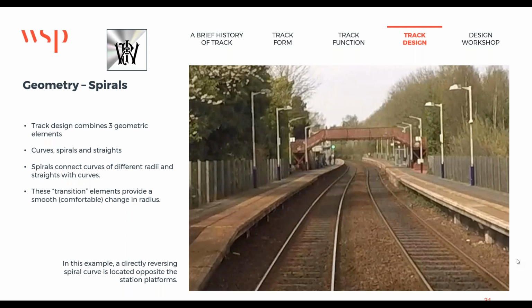Okay. And I'll digress to ballast ramps first just to cover that one off. The ballast ramp rule, which says the ballast ramp shall be created, which will be line speed divided by 6. Right. Well, there's an empirical value plucked directly out of midair. Right, there you go, a paduma. So ballast ramp line speed by 6. And I say, okay, well, that's fine. But on shorter things, track off jobs, bridge jobs, 20-meter bridge, 90 mile an hour track, you've got ballast ramps, 17 meters either side of that, but longer than the bridge itself. So your track disturbance is more than 100% more than what you were originally going to do.